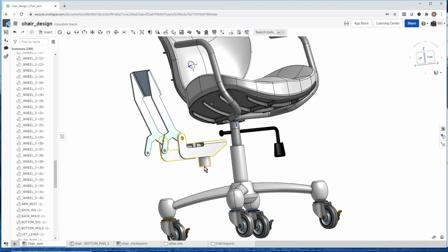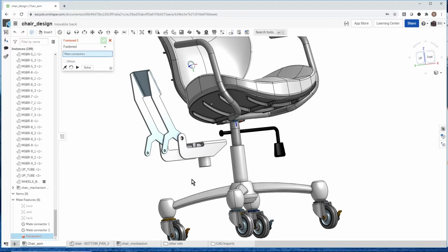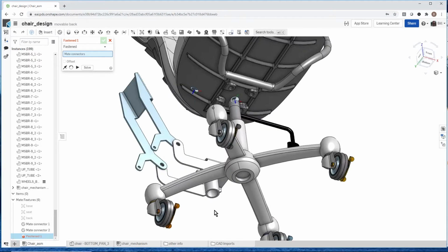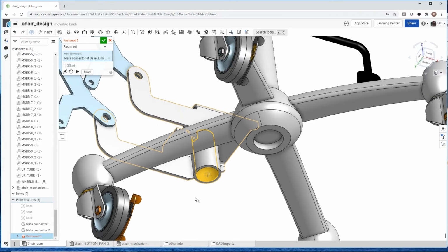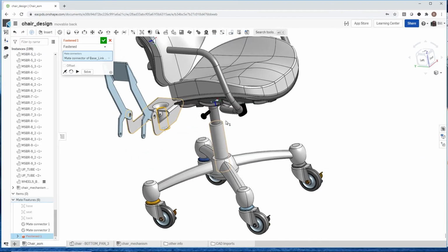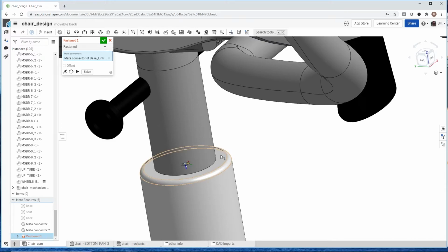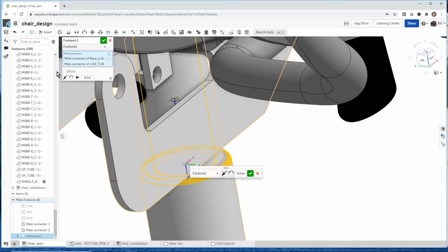So now I just need to replace this, just fit it on the pole here. So we can just do a real simple fasten. Actually, I'd probably put a pin joint there so we can rotate. Then over here, I want to put them in the center of this guy. And then we need to rotate him. Rotate it about the Z-axis, like 90 degrees.